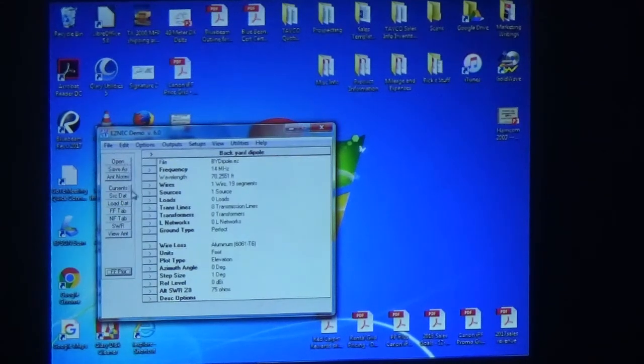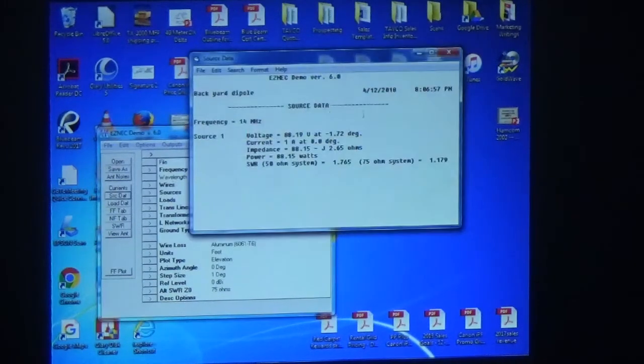Over here, remember I said these were all the inputs and the global plotting display characteristics. Over here is the output. Source data. There's the actual data, and on some of the plots you get this information at the bottom. But for the wire you're analyzing, at the frequency you're using, and the source placement, that is the impedance. So it's resonant. I mean, it's minus J.